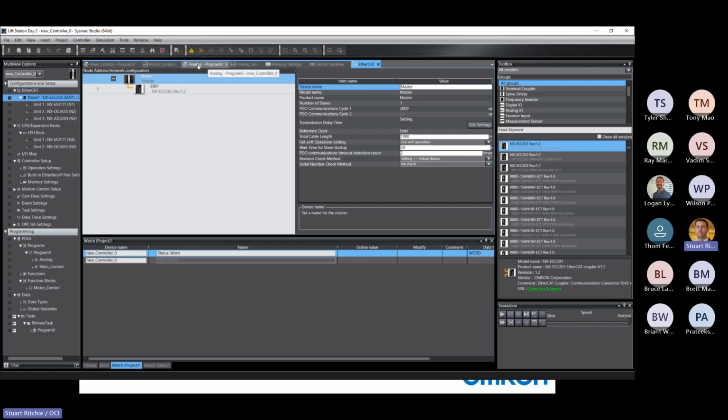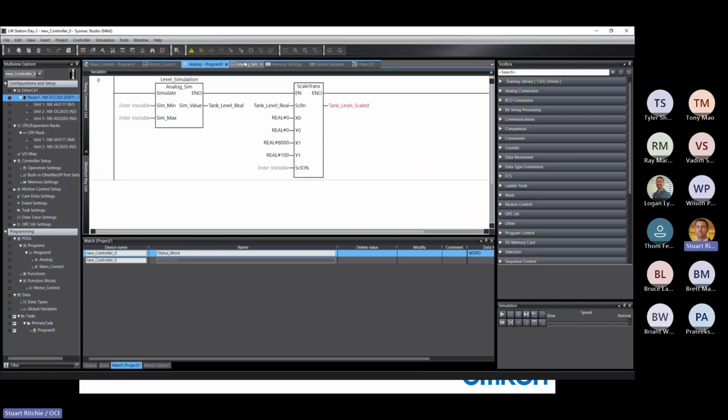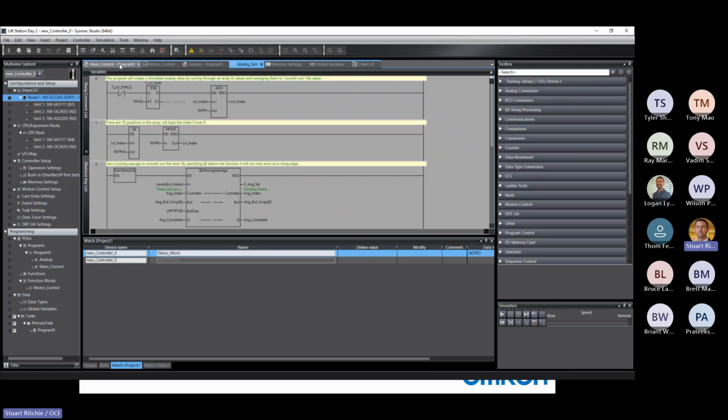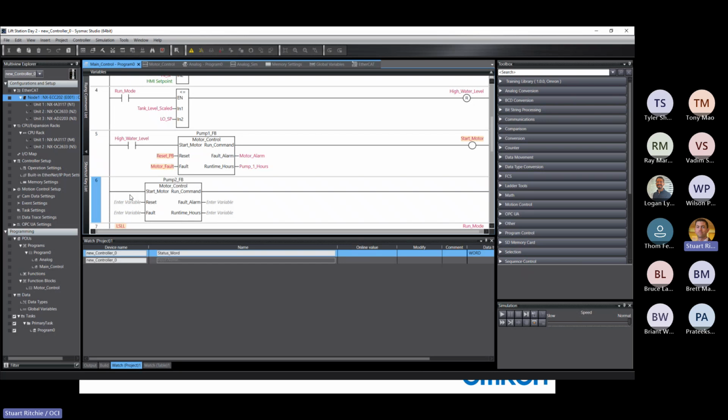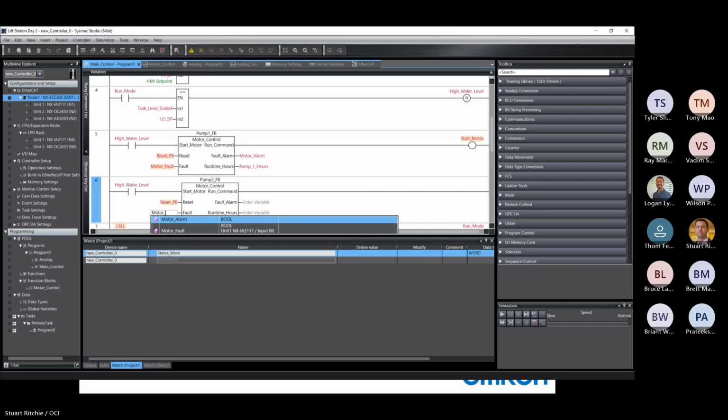But for the purpose of simulation, we're just going to create global variables that we can map in the future to our second pump. So high water level will be the same on our input. Everything else will have a pump 2 suffix on the tag. P2 to keep things short.